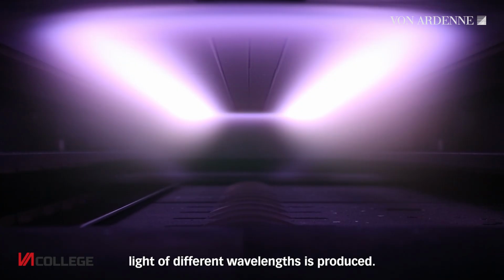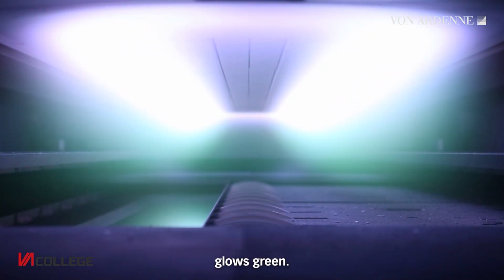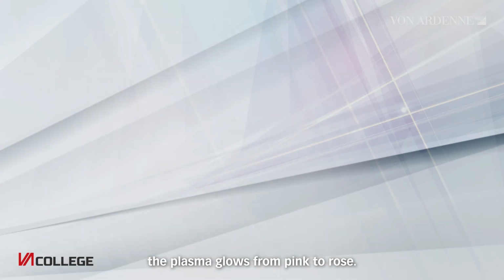And the light? Well, depending on the gas and the target material used, light of different wavelengths is produced. A copper target in an argon atmosphere glows green. If silicon is sputtered with an addition of nitrogen, the plasma glows from pink to rose.